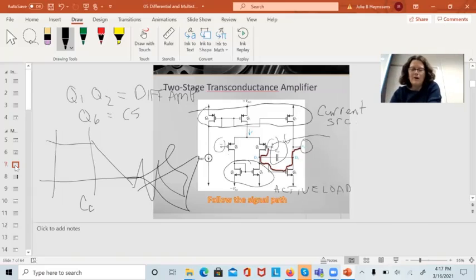And I'm also controlling the stability of the circuit. I lose some bandwidth, but I'm going to gain some stability. Is the Bode plot for the common source? This is the Bode plot for the whole amplifier. Oh. Yeah. There's a big mess at the end. That's what that represents, is the big mess at the end. The compensation cap puts a pole frequency at a low enough frequency that I can ignore the whole big mess of what's going on on the inside. Oh, okay.